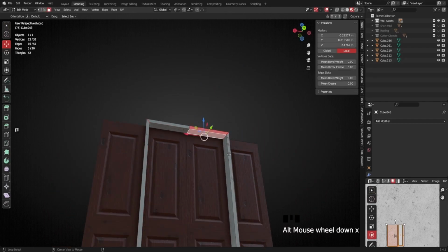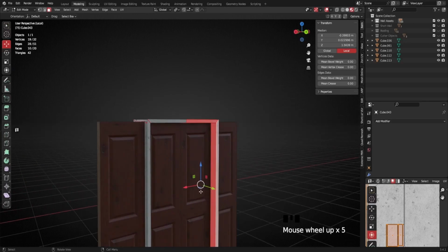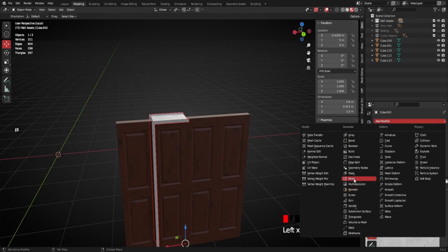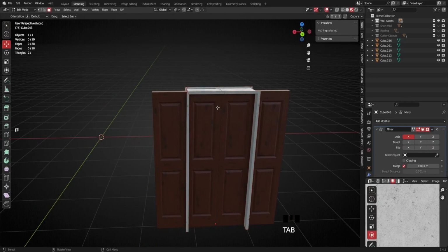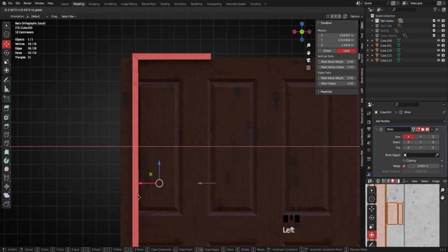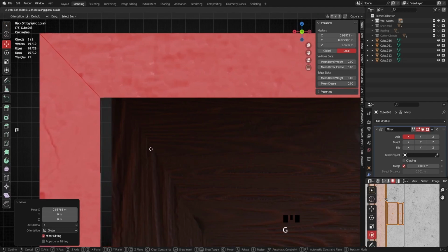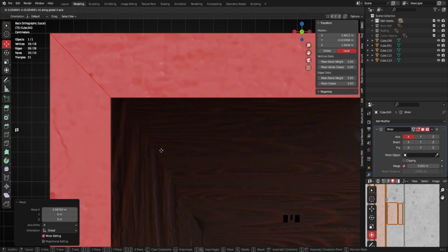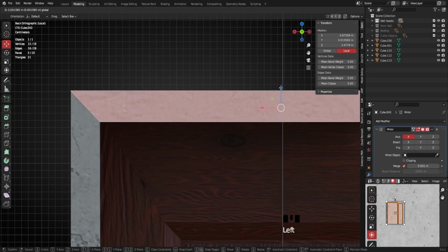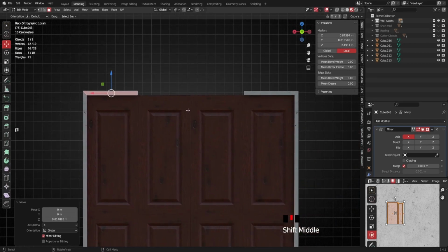I'm going to give this a mirror. So I'll remove half of it, delete faces. Now I will give it a modifier, add a mirror. Now I'll get to edit mode, polygons, select everything, and go front orthographic again. And I'm just going to pull this to the side and let the mirror do the work on the far side of it. So I just want to move it to the point where there's a slight gap in the door. Now I think I need to move the top a little as well. There we go with that.